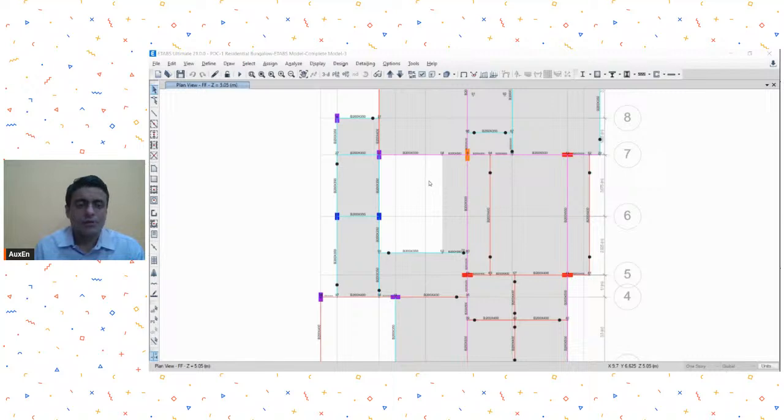Because the vertical acceleration has a constant function value, as we just saw, which is 2/3 into Z by 2 into I by R into a fixed value of Sa by g, that is 2.5.